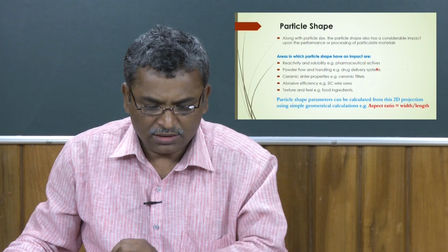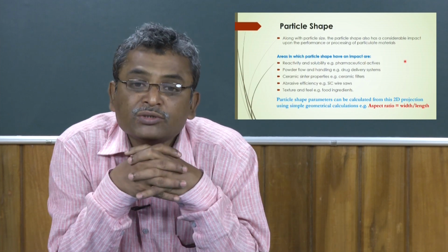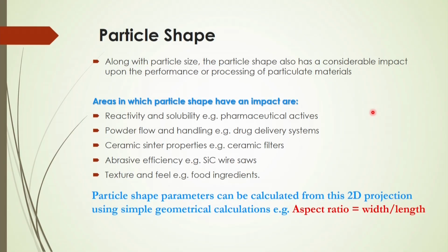And then particle shape is also important. All the particles you will not get the same in size. Of course, some particles will be larger in diameter, some particles will be rectangular, some will be cylindrical, some just rod like, and some even irregular in shape. So, the shape of the particles is also very important to analyze the fluidization behavior in the fluidized bed.